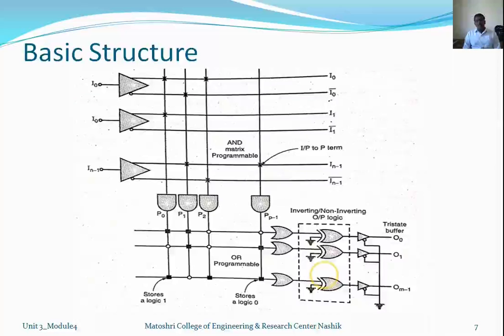In this basic internal structure of the PLA, you can clearly see a NOT logic gate array, which we call the input buffer array. If I0 is in non-complemented form, it is available from this data line. If it is complemented, it is available from this I0 bar line, the complemented form. So both lines are available in this way. The number of logic gates is multiplied by 2, as each has two outputs, so that many data lines are available in this PLA.